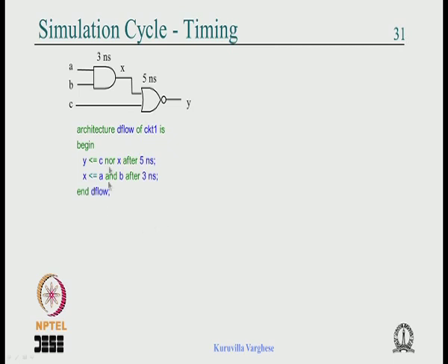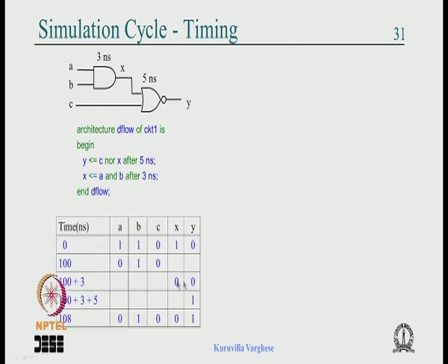It does not matter however many statements there are, whether there is feedback, in whichever order, and instead of the AND gate there is a very complex circuit, this game works. Concurrency is resolved by a very simple method of looking at the right hand side of assignment where the event happens, that is computed, and a new event happens, that is ordered properly, and it proceeds. So that is what is shown here.